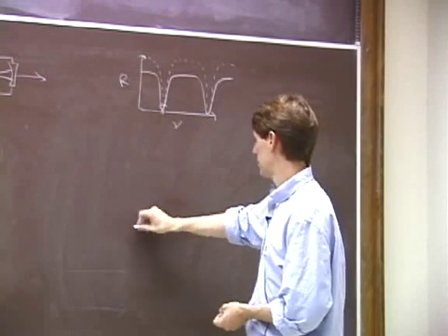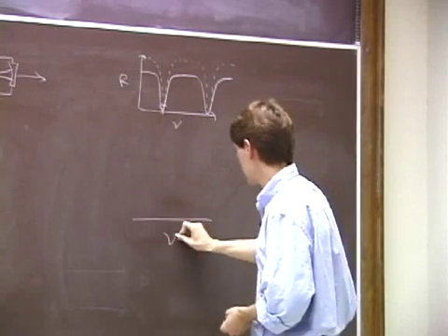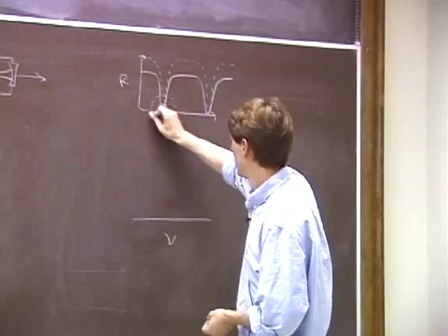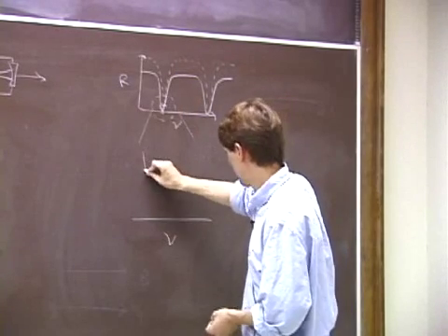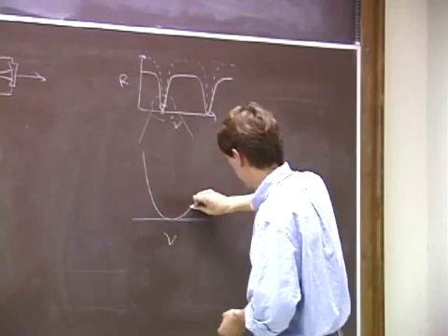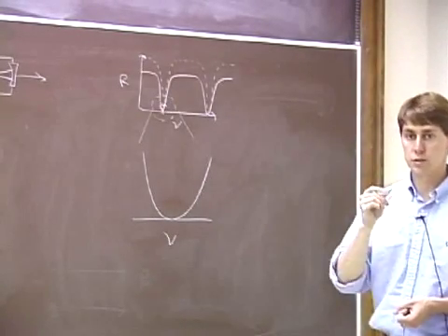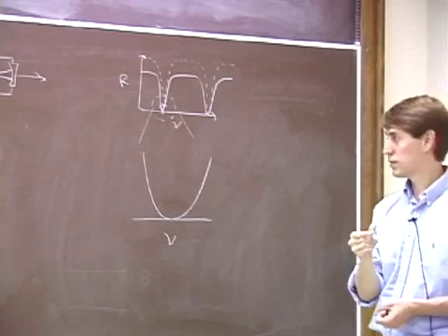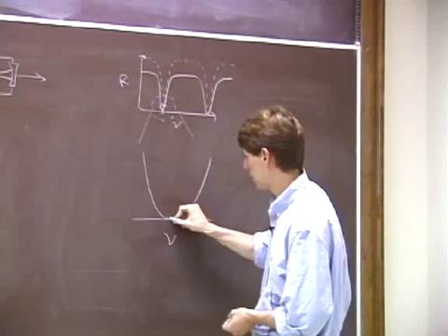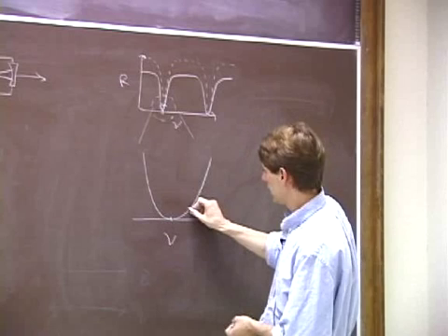And I'm going to draw a close-up of this here. This is the laser frequency. So we're going to modulate the laser frequency and try and measure the derivative of the reflected power. So we'd like to operate on this point. But say we're a little bit off this point.